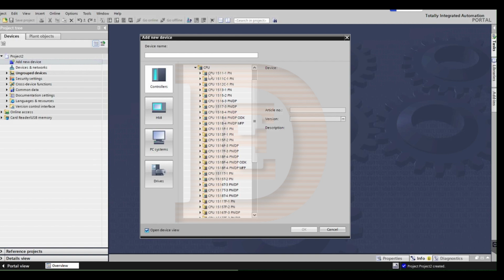If you look here, PLCs are numbered with respect to the power they have. The 1200s are the low-end kind of PLCs. They're low end to the applications; they may not be low end to your application. If your application is not a big machine, does not require high speed, and does not interact with many external devices, you're okay with the 1200.